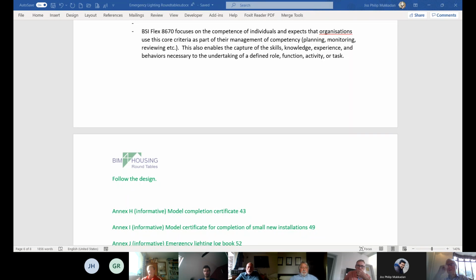Well, the lighting level requirements ignore reflection. Yeah, so anything with reflection should be on top. This is to do with luminance qualities, Chris, more than anything else, specifically for trips, slips and falls on staircases. It's not necessarily to do with reflective light. True. So in the information for question 2, we need to put in the luminance effect of wall covering, or just luminance effect. That should be ignored in the design, because we never know how someone could come in and change the decor. No, not in the design.